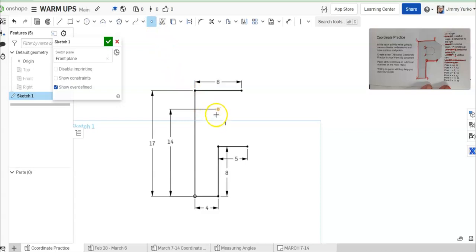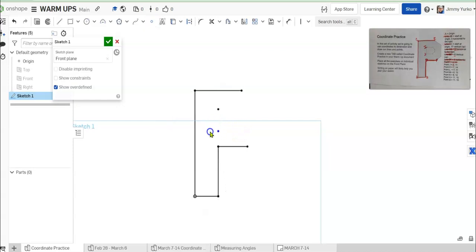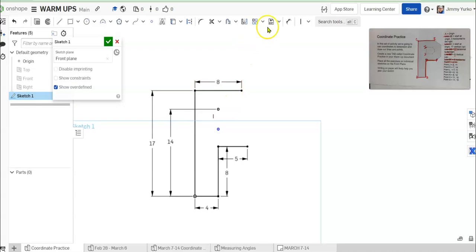So it's going to be, again, lined up with the others. So let's just hover over it, move down, click and release. If I escape, go to move that. See, it can move up and down, but not side to side. So we need to put a dimension on it. I click and release on that, click and release on the origin. Point J is 11 high.